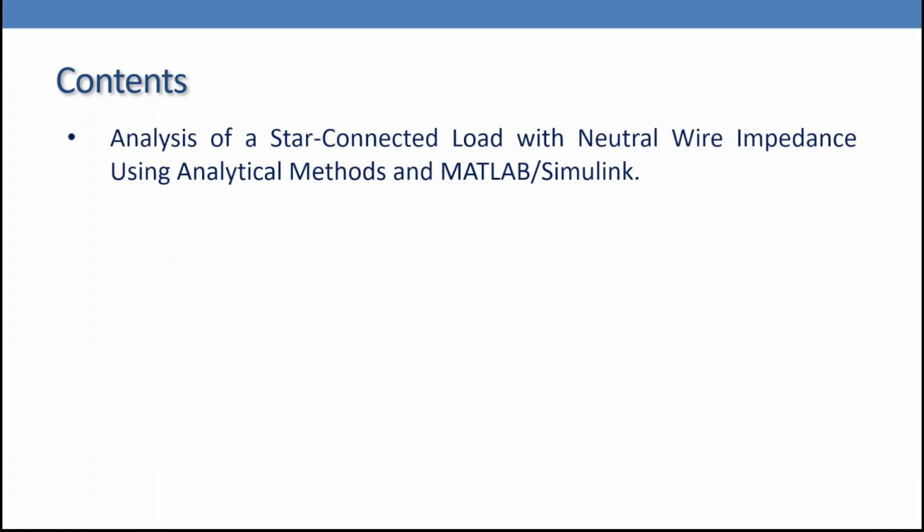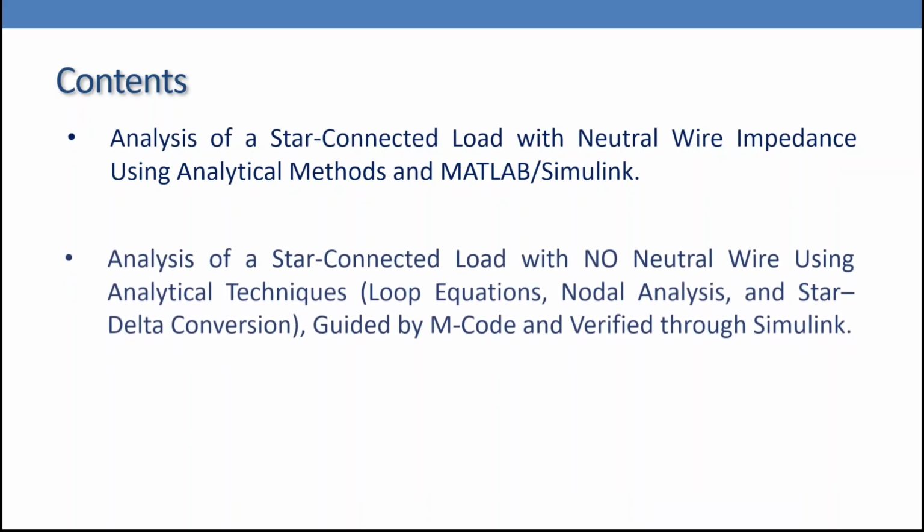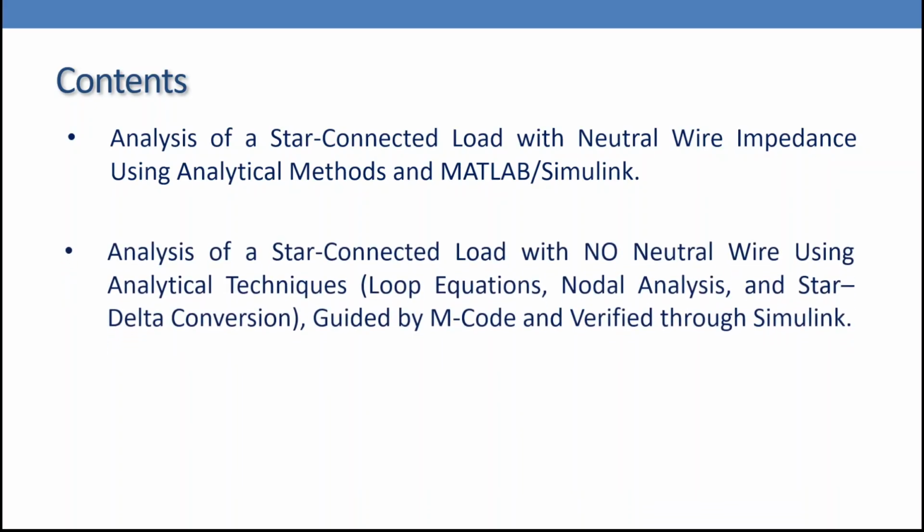Analysis of a star-connected load with a neutral wire that has an impedance, using the analytical method and verifying this method using MATLAB Simulink. Also, we are going to analyze a star-connected load with no neutral wire using different analytical techniques such as loop equations, nodal analysis, and star-delta conversion. And these techniques are guided by MATLAB M-Code and verified through MATLAB Simulink.